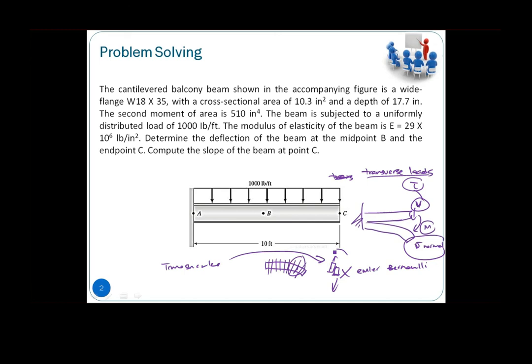So this particular effect itself will mainly affect our stiffness. If you're talking about our stiffness matrix for the elements, we have a 4 by 4 symmetric matrix, right? So here it is referring to UI1, UI2, UJ1, UJ2. When you consider Timoshenko, it will affect your rotation parts a lot.